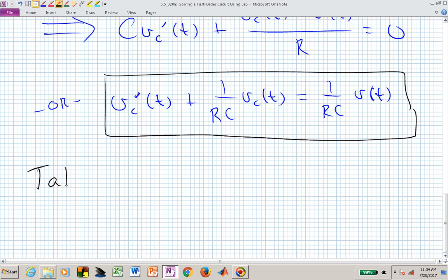So let's go ahead and solve this differential equation by using Laplace transform techniques, which means let's Laplace transform this time domain equation and get into the frequency domain. We'll do our manipulation, try to find the structures that we want in the frequency domain, and we can immediately, using the transform tables, pull those back into the time domain to find the time domain waveform for our voltage, V sub C of t, that satisfies that governing differential equation.